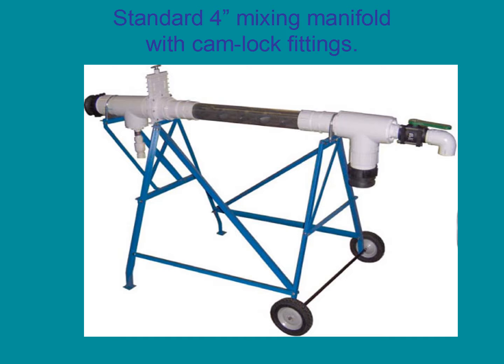This is a standard flocculator with a 4-inch inlet and outlet connection. This flocculator includes a polymer solution injection point, a steel stand with wheels to allow it to be moved in and out as needed. At the end of the flocculator, a 2-inch valve is used to sample the sludge to ensure that a good flock is being produced.